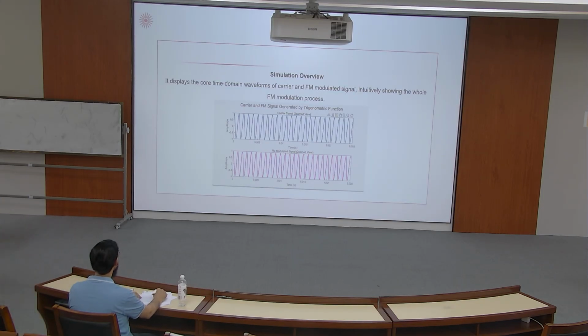The simulation shows the system can stably track frequency changes and accurately recover the baseband signal. The demodulated signal has a smooth envelope and low distortion, proving reliable performance of PLL demodulation.